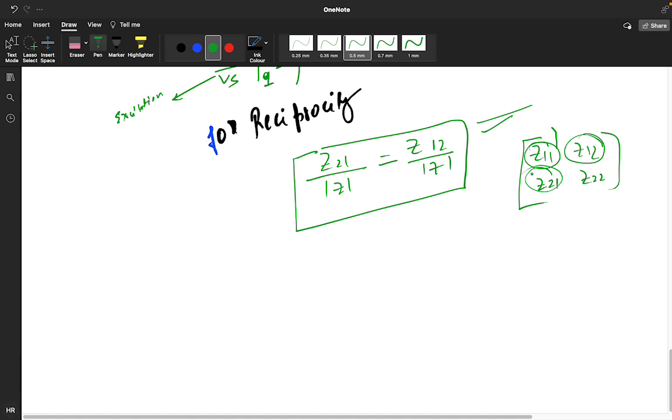And we know the relation between Z parameter and Y parameter. So the result for the Y parameter is minus Y12 divided by determinant of Y, and Y21 divided by determinant of Y. This will be a minus sign, because this is Z11, Z12, Z21, Z22.